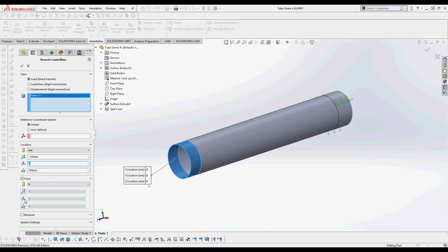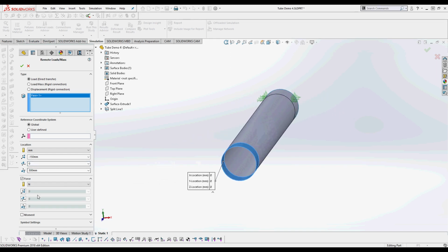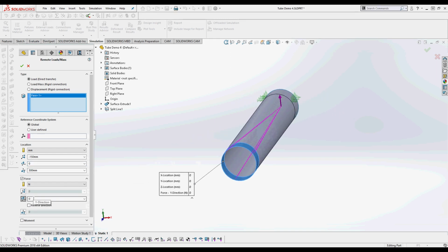And finally, we are going to specify a load that is perpendicular to the off-axis direction. So you'll see in a moment what exactly that means. And the magnitude of this load doesn't particularly matter, so we can just do some reasonable value. Say 500 newtons.